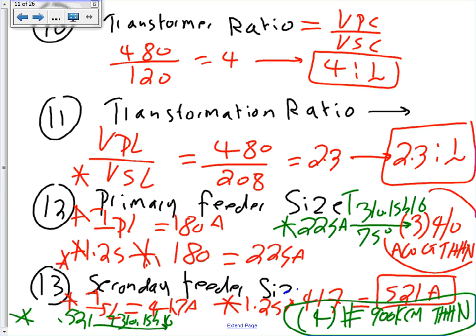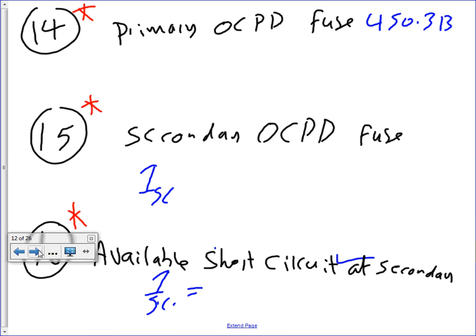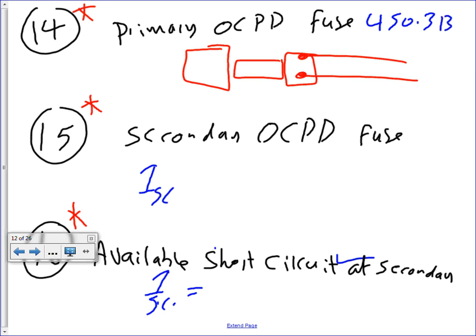Let me know when you guys can move to the fuses. If you parallel, do you end up putting 6 fuses or could you still use 3 fuses? 3 fuses. Good point. When you parallel, here's how they do it. Here's my fuse and here's my fuse holder, from both sides, and then your conductors will be landing here. But it's still one fuse.